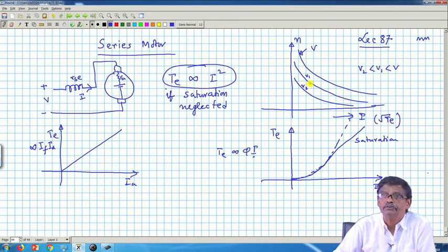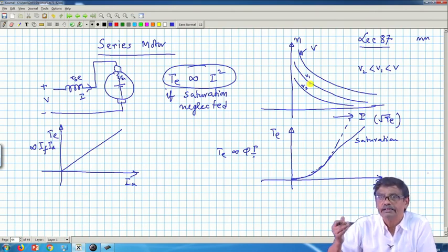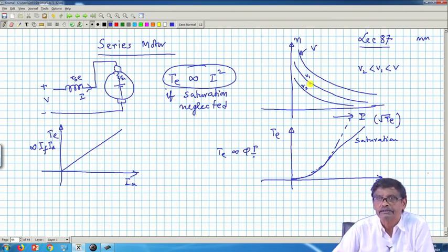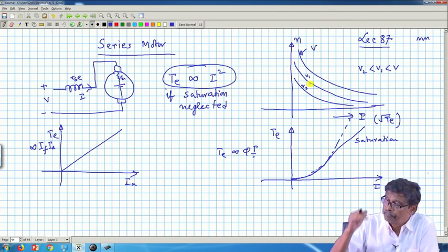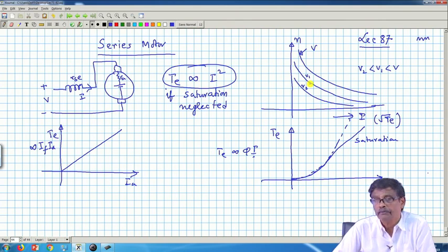Above the base speed, one could increase the armature voltage, no doubt, but armature voltage has got a rated value, and up to that only I will be able to control the voltage. So, if I want the speed above the base speed or rated speed of the machine, field control was adopted. Weakening the field current means you are raising the speed higher and higher.